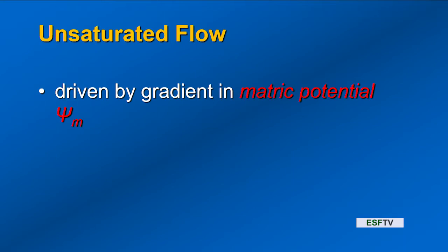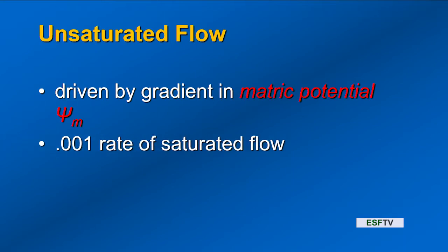And it's always from higher potential to lower potential. The rates are orders of magnitude lower than saturated flow, 10 to the minus 3, 1,000th the rate. So now we're talking about a relatively small movement of water. It's not unimportant, but in terms of the amount of water that moves by saturated flow, it's a very, very small fraction.